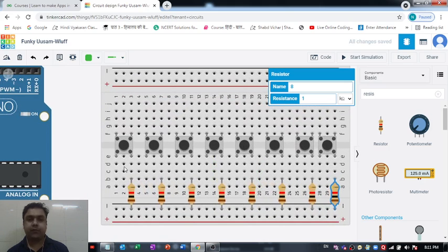So that's what I have done. I've connected all these 8 push buttons with the help of these resistors to this negative terminal of the breadboard. Right, now let's do one thing. Let's connect this terminal 1A of all these push buttons with the positive terminal, because this one we have connected with negative, so the first one needs to be connected with the positive terminal, of course.